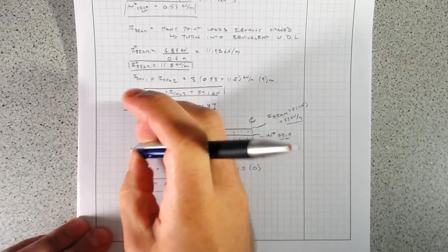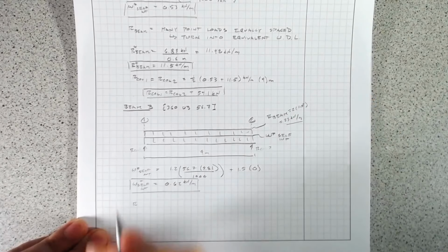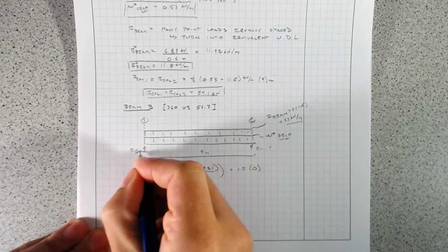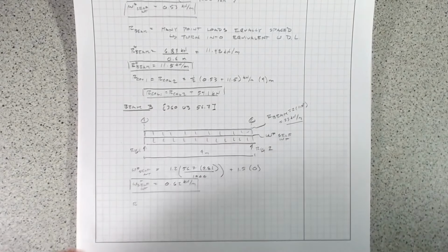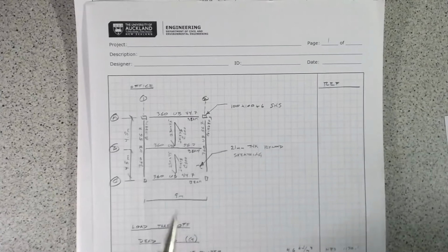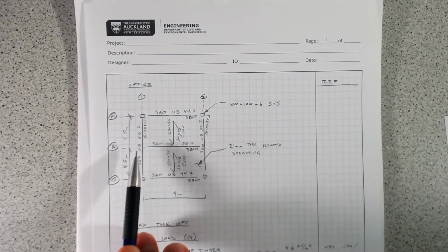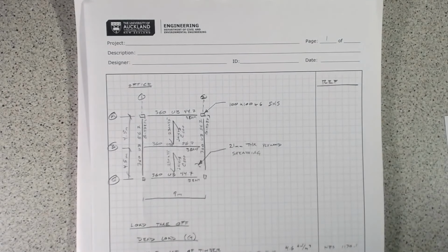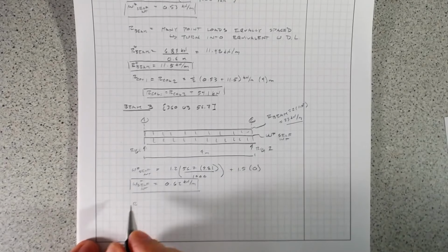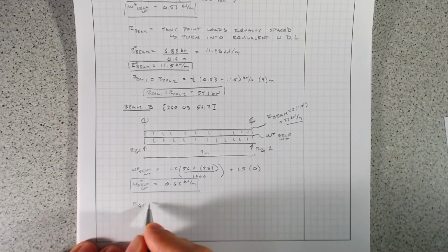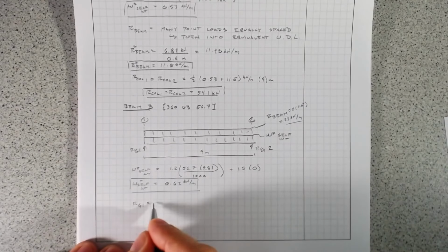Instead of the column, that's my fault there, we'll call this RG1 and RG2. And that's because this beam B is not supported by the columns, it's supported by the girders. And so this is going to come in as a point load here and here. So, apologize for that error as I'm going through here.